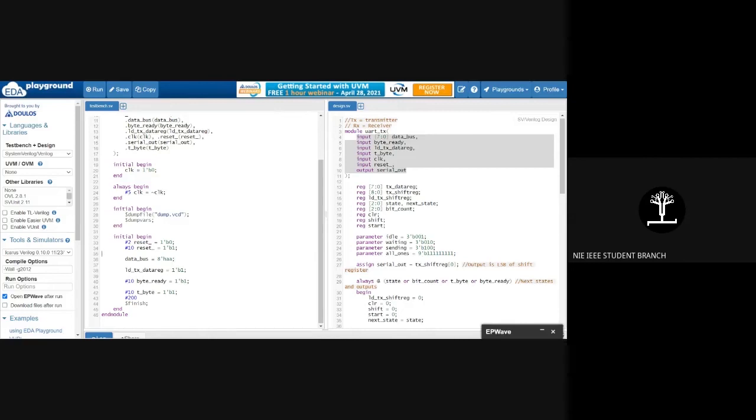Okay. So that is what I've done here. At the same time, I'm also pulling this high. That is, I am telling that data register to go high, that is, from the bus, take it to the data register. Then after some time, after the state machine has settled, I'm asserting byte ready, telling it that okay, you can take the byte and it is ready for transmission.